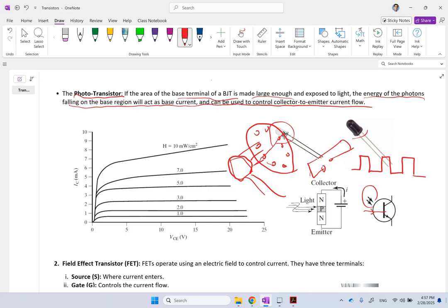So if you count how many of these pulses you have, you can count how many of these holes have passed between the transistor and the diode. And let's say if you have, for instance, 30 of them every 12 degrees or so, then every 30 pulses means one full rotation, correct? So it tells you exactly the angle that your system has rotated.